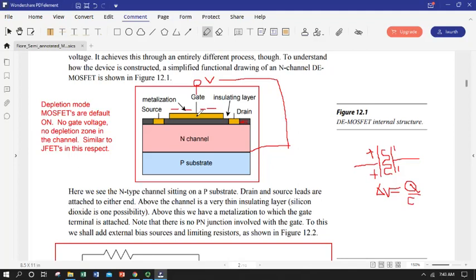Well, in a MOSFET, the metal layer of the gate and the fairly conductive and negative charge carrier rich channel below it, or a positive charge carrier channel in the case of a P, form basically the conductive plates of a capacitor at the gate. Okay, so here's one plate, and here's effectively the other plate, the N channel itself, with the metal oxide layer forming the dielectric.